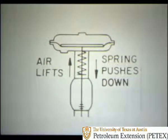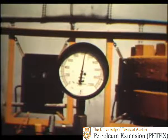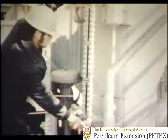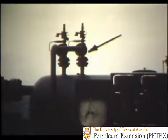These features are the pressure gauge to indicate the internal pressure of the separator and to set the back pressure control valve, the gauge column for viewing the liquid level and to set the level controls. We've seen that it's important that both these features, the pressure gauge and the gauge column, are in good condition. Else how could you know that your equipment is operating properly? The next feature was the safety relief valve to prevent overpressure of the vessel.